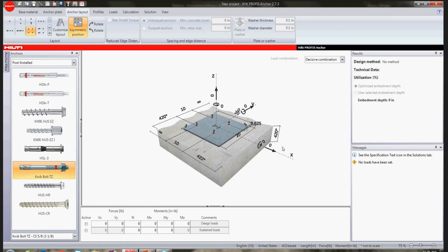The second portion that I'm going to take you to in the base material tab is the edges function. The edge function allows you to input the fixed edges in your design, and the way that these arrows are laid out will be a standard XY axis. To emulate this and show you, I'm going to zoom out of the model and rotate using the right-click function on my mouse, and orient my design to show you where our fixed edges are going to be. You'll see there that positive Y reflects positive Y, and so on and so forth. I'm going to bring this back to an isometric for the remainder of this model.